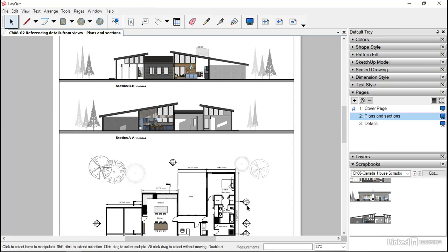And I often see from some of the students, they put the section line in and it's pointing in a direction that doesn't actually match what we're looking at. Okay, so they've got the orientation of this thing wrong. Maybe this thing needs to be flipped, or this thing needs to be set differently. So it's kind of important that you get the direction of travel right with these things.